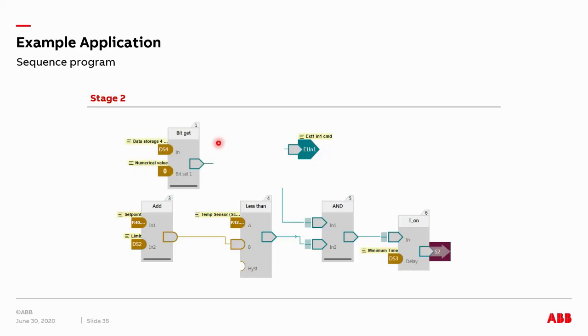And we want to make sure the time is there as well. I'm sorry, not the time. In this case, we're making sure it's not being told to shut off. So I look at data storage 4, look at bit 0, connect it in. I tell the motor starter to start, and then I tell the fan to start. That's what I'm telling them here. I come in and then check to make sure if the temperature ever drops, drop down to stage 1.